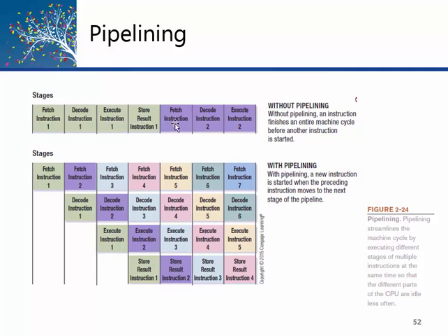And then it takes another series of clock cycles to fetch, decode, execute, and then we would have store for instruction 2 if our figure continued on to the right, fetch, decode, execute, store for instruction 3, and so on. But at the bottom, we're using this process called pipelining. And this is kind of a cool, elegant idea.